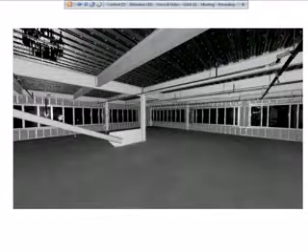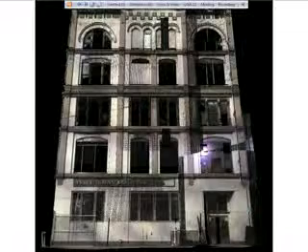So what we're looking at here are actually some different point clouds. These are scans that we're taking of a facility out in the Boston, Massachusetts area, and you'll notice that when we get them to a very high resolution, they almost resemble a photograph. So this is an interior shot where they use the scan. This is very useful for working with as-built information. If you're going to be coming in and maybe doing a fit out of an existing facility, now you have an accurate representation of all the material, the metals, the structural systems, as well as fire sprinklers, and some additional elements that you might find in a structure like this.